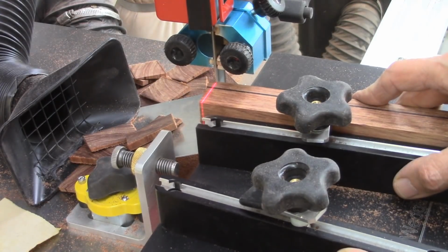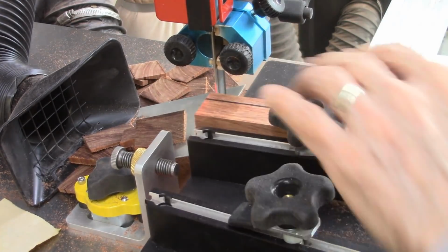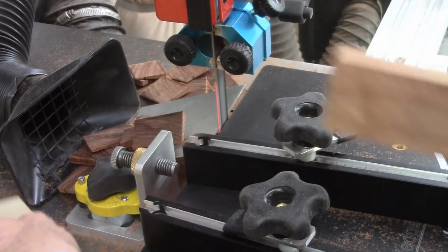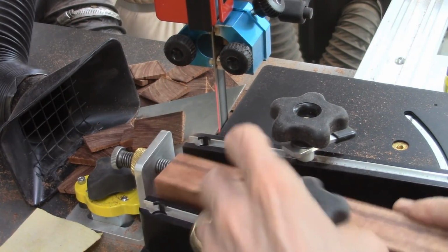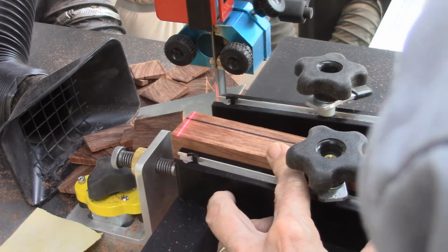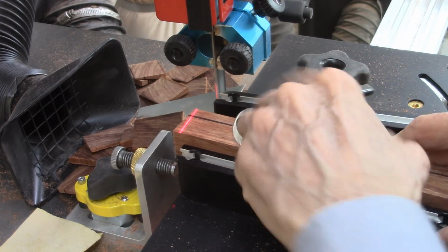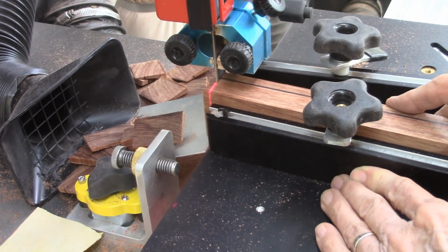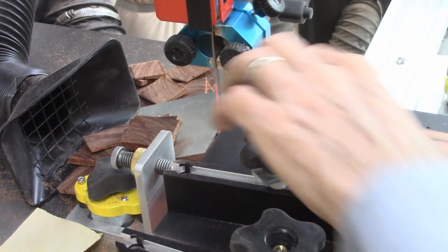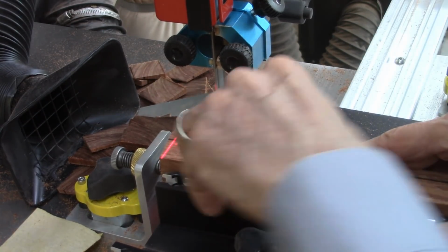I set up the Accu-Wedge system to cut 48 segments per disc. I adjusted the outside width of the padauk segments to be 0.21 inches. Each of my disc blocks is 1.5 inches high, so I need a total of 5 of these disc blocks to provide for the 47 discs that will be cut from these disc blocks.